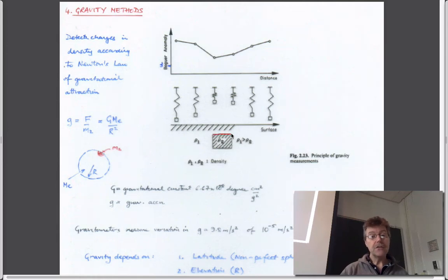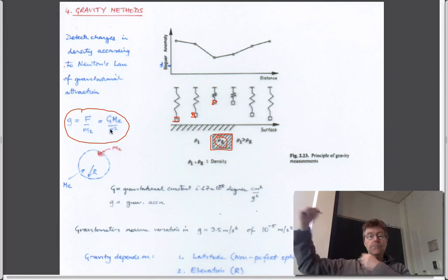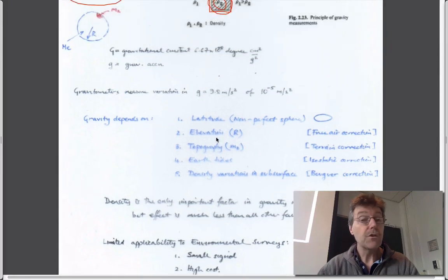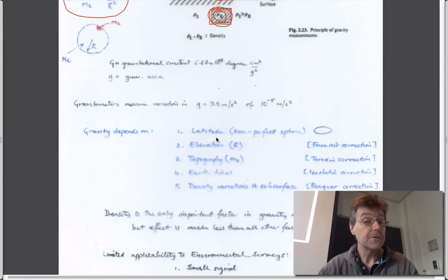Likewise, if instead of having lead, you cut a hole out of the subsurface, so the density of this was the density of air rather than material around it, if you measured the attraction of a weight to the Earth as you go across this section, you'd find that it's less attracted to the Earth here because there's a mass deficit. And you can use Newton's law of gravity to define that. Newton's law of gravity says why the moon is attracted to the Earth and goes around it, is held where it is, and likewise says why, if you measure the attraction of a weight in a measurement instrument, it's attracted to the Earth, but also the Earth with a small amount removed from it. And so if you can measure the gravitational field very accurately, you can pick up the location and the size of different things in the subsurface.